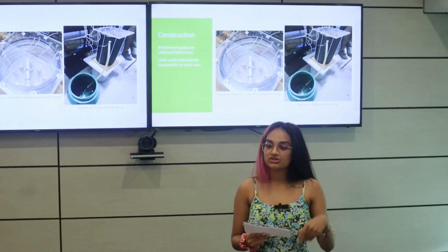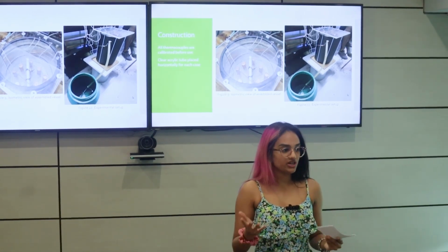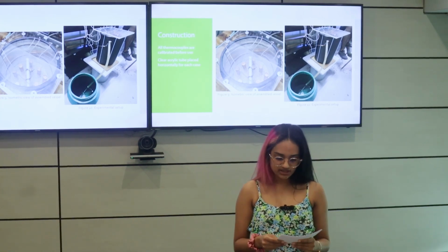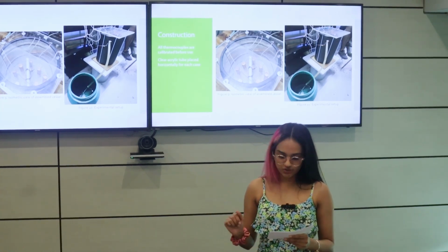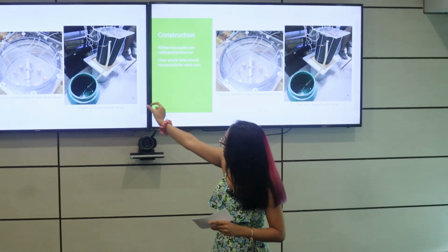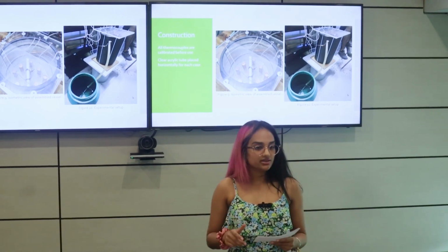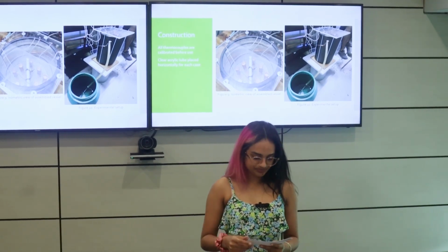Due to the fact that I was using phase change materials, it is important to be able to monitor when the phase change occurs. For that reason, I included a single clear acrylic tube, as I've shown in figure 9. You can see it here, just in the middle there. That's the paraffin wax, in order to monitor the melting process during testing.